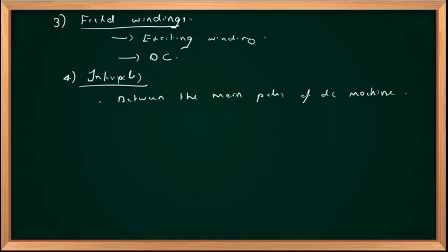And the shape of this interpole is tapered. It is not perfectly rectangular. It is tapered at the root to avoid magnetic saturation.